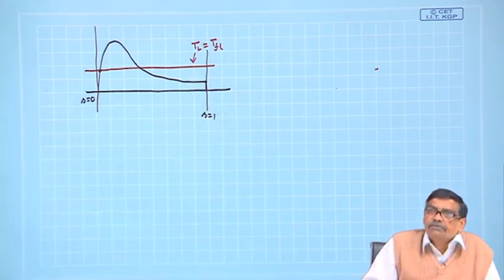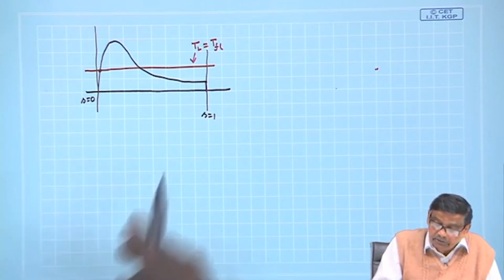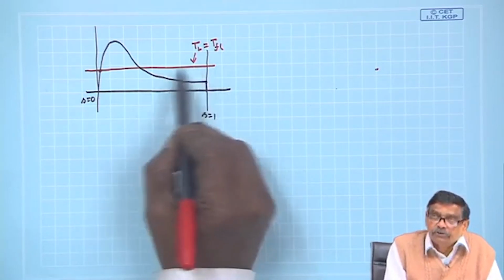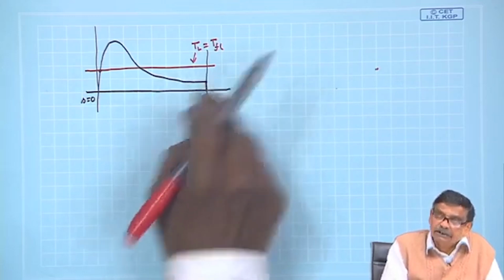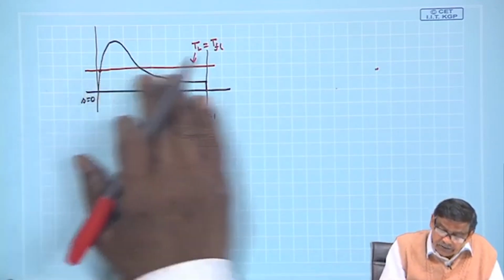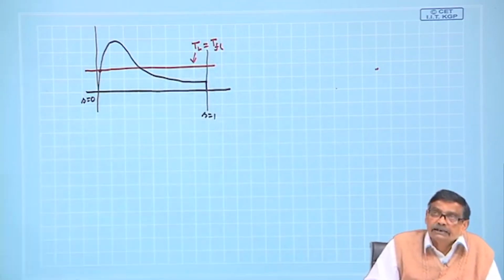Therefore, the motor will fail to start, because we have not produced enough starting torque to overcome the opposing full load torque, which is already present. Okay. Therefore, this machine cannot be started as it is with full load mechanical torque connected to the shaft.